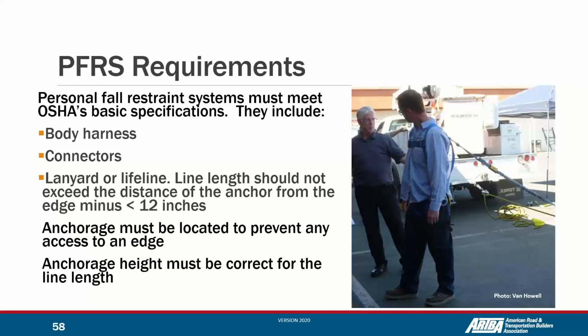Okay, and this is allowing us to go to the next level of protection, which is administrative control. For example, training, rotating our workers, creating some restriction for some work areas in which it's possible to have more people falling. For example, in a place in which usually we have 10 workers, maybe we can restrict the location to only 3 workers to prevent fall hazard, only authorized personnel in this area. So we can create some administrative rules to improve safety.